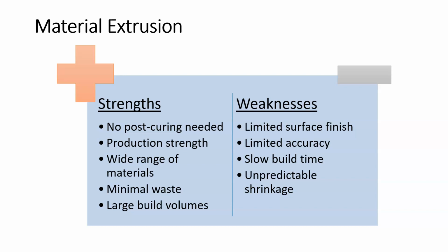You are going to have some contraction of the plastic, which is going to affect dimensional integrity. It's not great. There's not a whole lot of shrinkage going on, but depending on the accuracy level that's needed, it might impact whether you decide to use it or not.